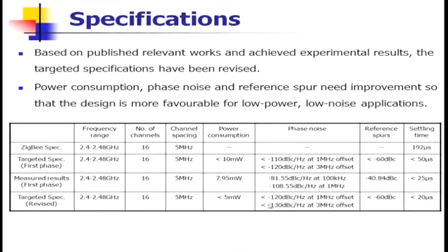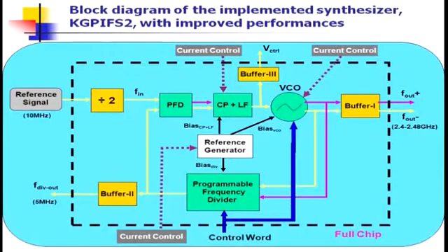And the kind of phase noise performance is minus 120 at 3 megahertz, 130, and the reference point is 60 dB. Since I got an advantage in my settling time of 50 microseconds, why don't you target 20 microseconds? So, this way you are increasing your own benchmark to improve the performance. Here there are some things which require a little bit of study.